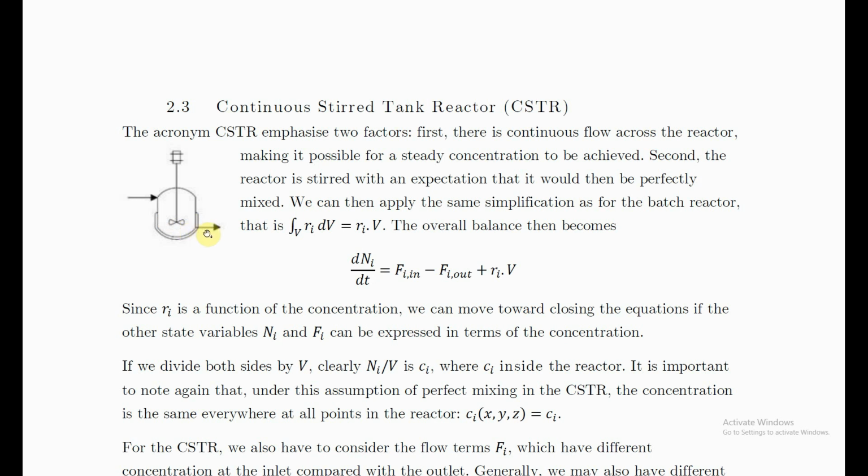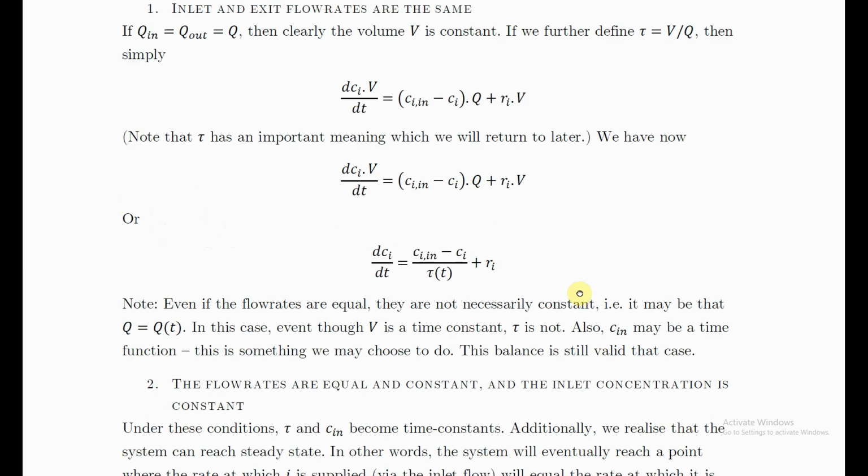If you were feeling that maybe my production rate or my concentration of product here is too low, then you might want to try to increase the reactant concentration. So you might ramp up, you might change the inlet concentration over time, and so influence what's happening here, which is fine. There's nothing wrong with doing that.